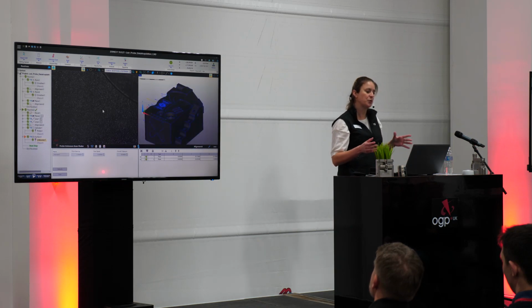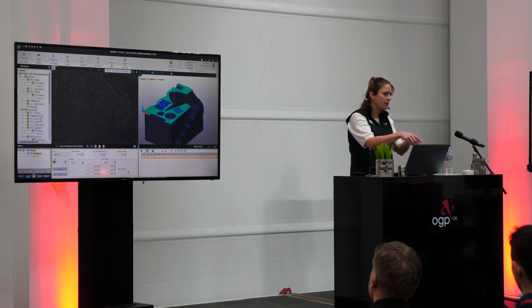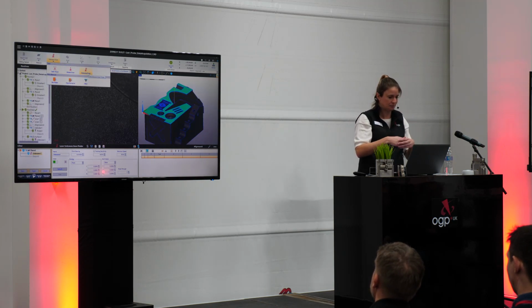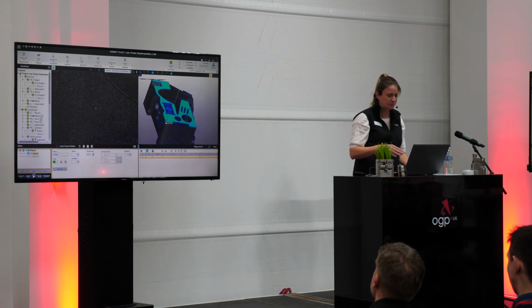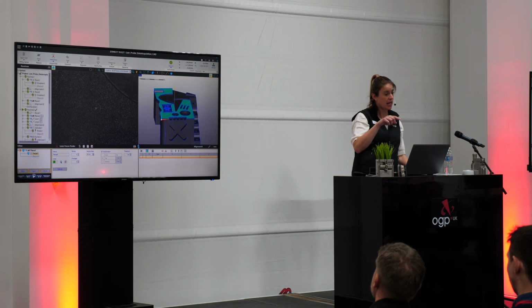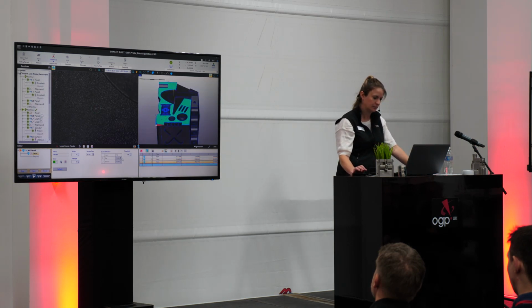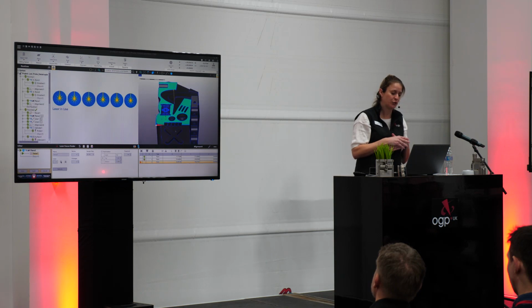And now I'm switching over to a laser tool, and this is a through the lens laser. So the video image is actually useful here because it's where the laser is going to scan. So again, I'm going to do laser focus points on the top of the plane, and I can just click on the CAD model where I want to take those focus points. Or I can use the path generation functionality here too.